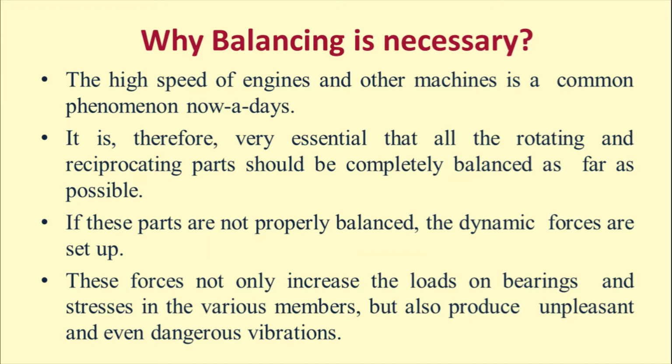That is a very tricky question. Now if these parts are not properly balanced, then dynamic forces are set up. These forces not only increase the load on bearings and stresses on the various members, but also produce unpleasant and even dangerous noise and vibrations.